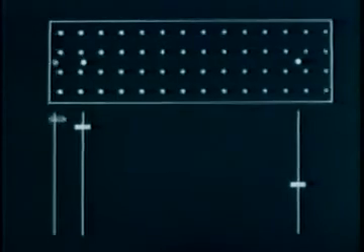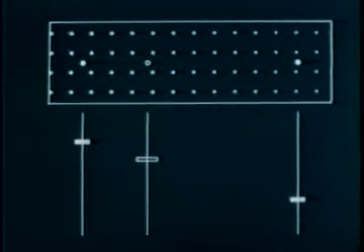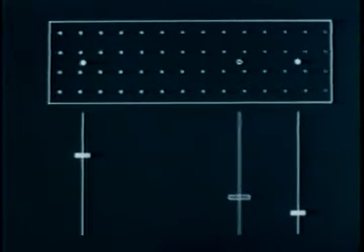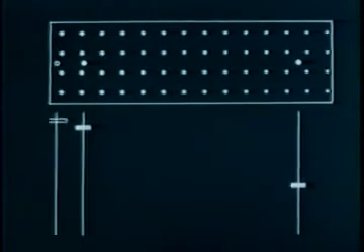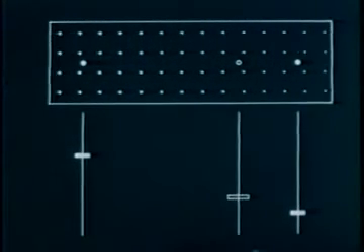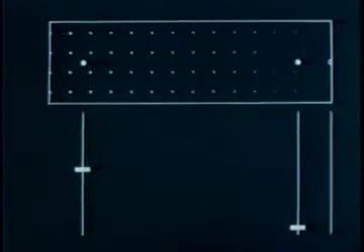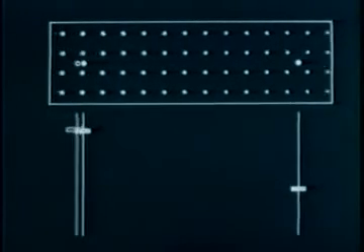Just as before, the only change experienced by the material point is due to decay. The change seen at a laboratory point is not, however, since new material of originally higher intensity is being swept past. To express the change experienced by a material point in Eulerian variables, we need two terms: the change of intensity with time at a fixed point and the intensity difference between laboratory points at a fixed time.